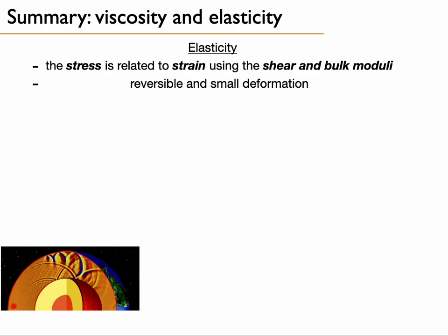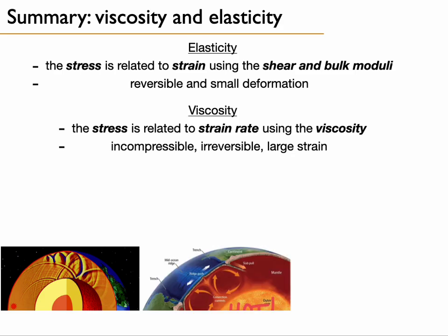So the summary, we have elasticity, and in elasticity the stress relates to the strain, and we have introduced the shear and the bulk moduli to quantify the magnitude of stresses. We have reversible and small deformation, and this model may be used to study the propagation of waves in the earth, for example.